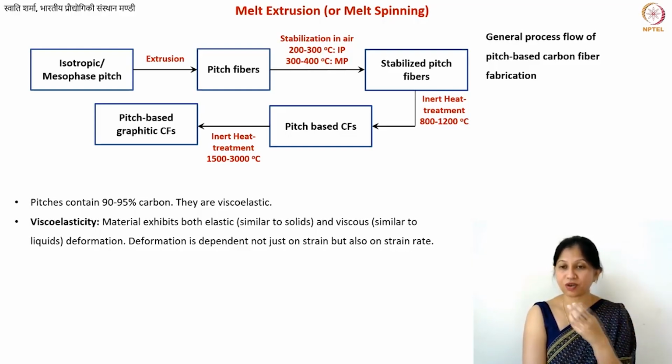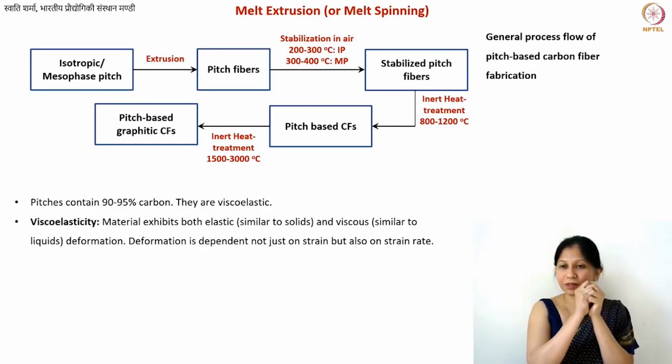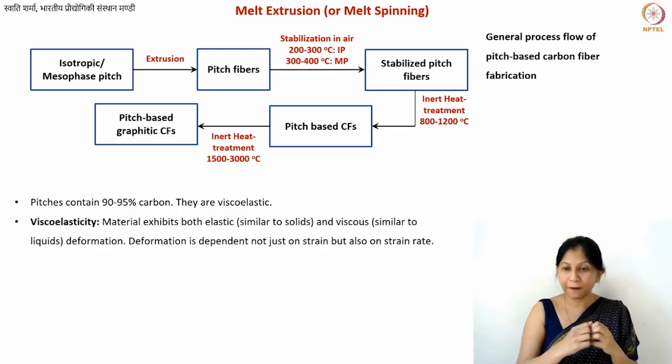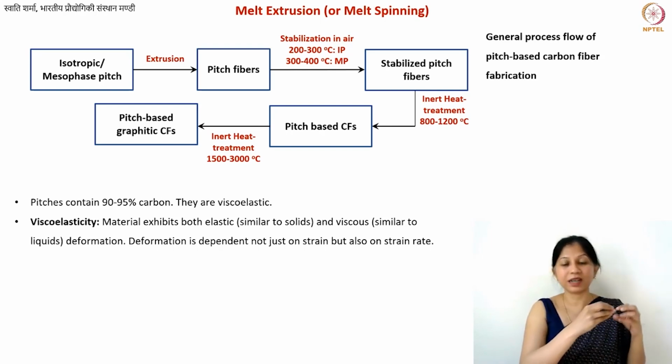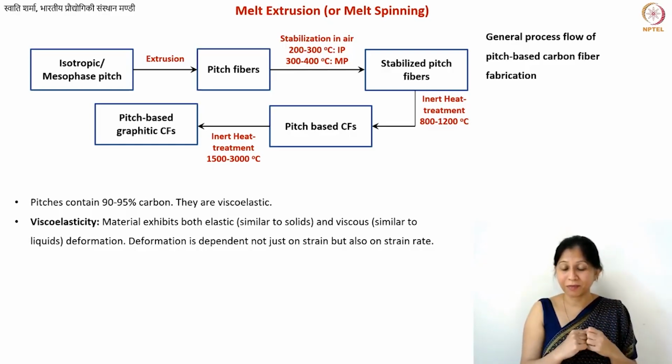Also in the case of pitches, you have hydrocarbons that are chain-like molecules, or in some cases sheet-like molecules. Now these chains can entangle, so they can form structures that are very difficult to open, so to say. They are entangled chain-like structures, but at the same time they may also have some chains that are floating, that are able to freely flow. Not all of them, but some of them. So you have partially solid-like properties.